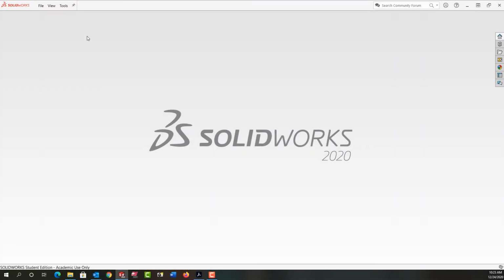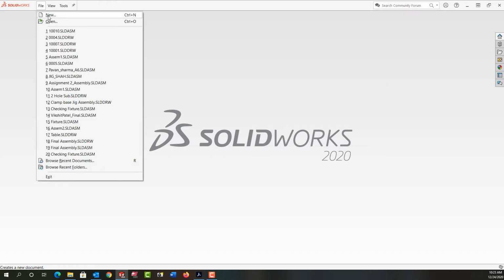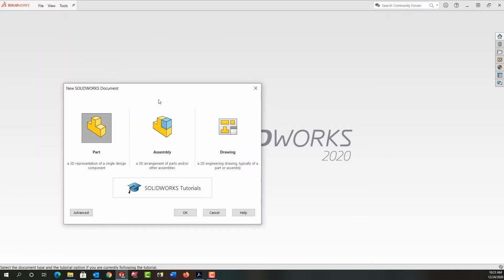In this video, I'm going to demonstrate how to start a new part and explain what we see when we first start a part in SolidWorks. So to start a new part, I'm going to come up to the menu and select File, New. And here from the Novice tab, we have three choices. I can start a new part, a new assembly, or a new drawing.